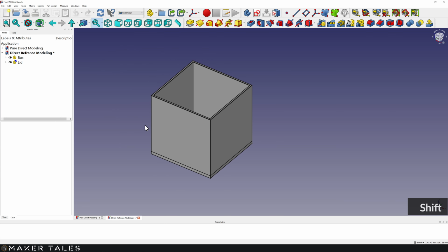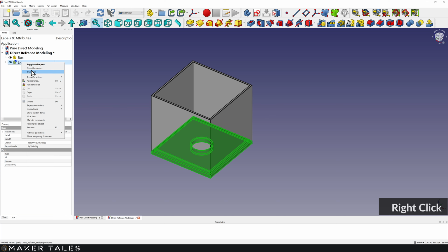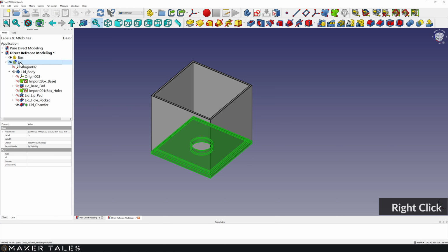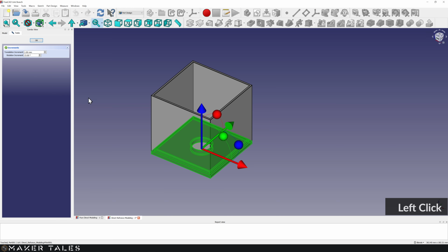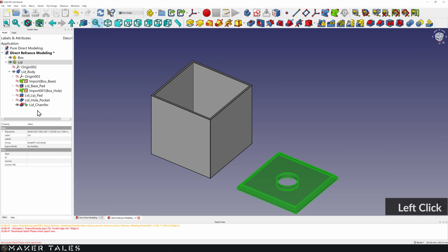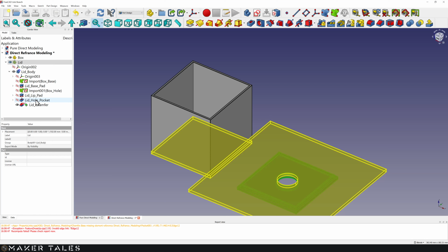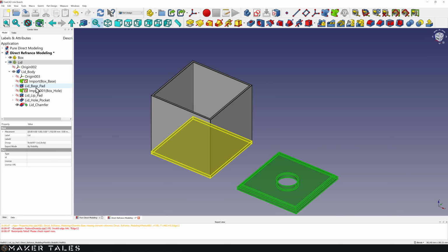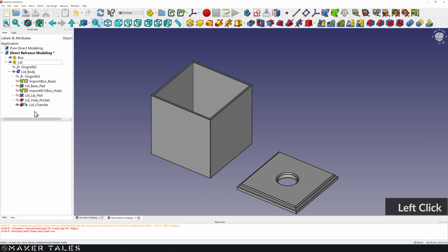Now, because this is so closely referenced to one another, we cannot move this through a transform. And let me just show you why. If we were to select this and go transform and then move this, click OK, well, we've just broken things. Things no longer really know what's going on. In fact, if we go over here, oh dear, that is definitely not what it's supposed to look like. What is going on there? This is because we have so many references going on.